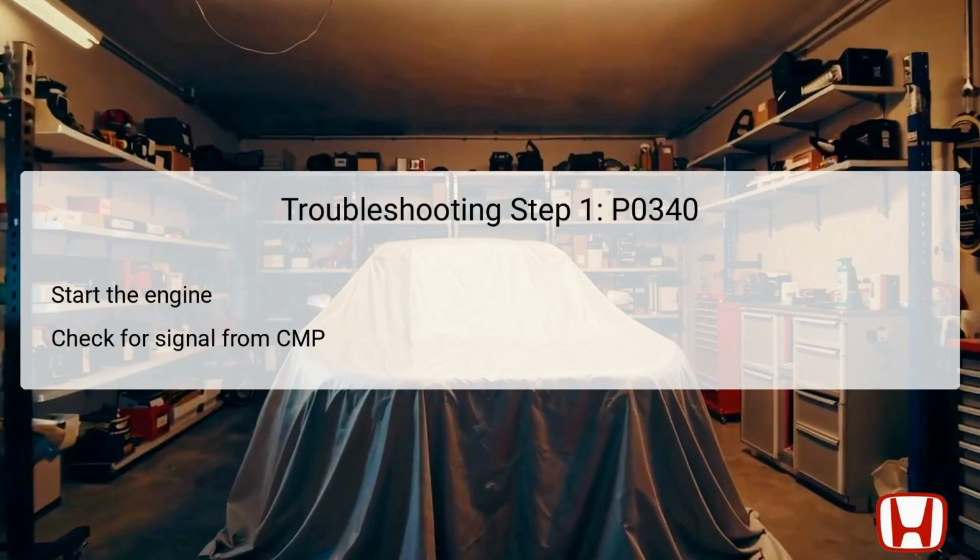The first troubleshooting step for diagnosing the P0340 code involves starting the engine to observe the conditions present at that moment. This stage is critical because it sets the baseline for examining inputs from the Camshaft Position Sensor A. If the engine fails to start or exhibits symptoms associated with this DTC, it provides initial clues toward identifying the issue.